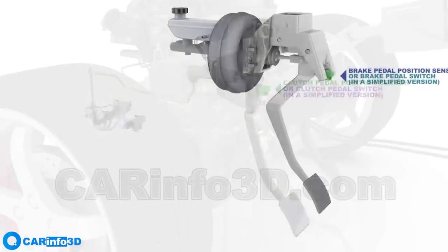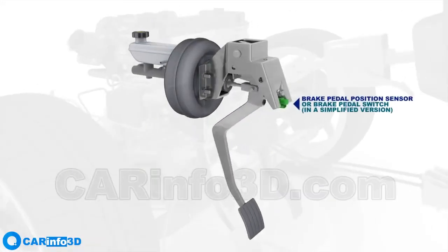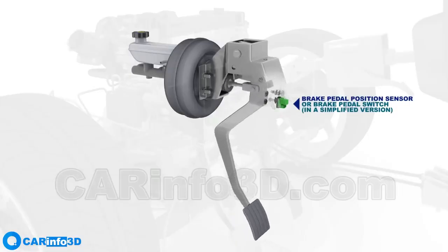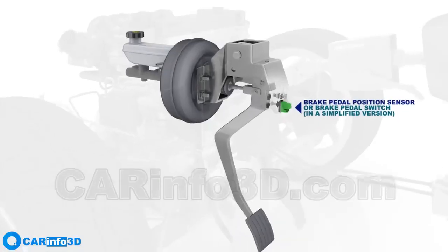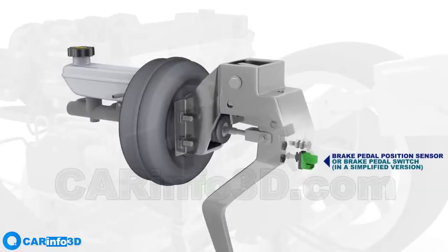Next, the brake pedal position sensor. It is mounted next to the brake pedal. In the most basic configurations, this sensor is a traditional switch that activates stoplights when the brake pedal is engaged. In more advanced systems, the control unit activates the stoplights when it gets a signal from the sensor. It can also perform additional functions, such as sending signals indicating the transient operation of an engine, turning off cruise control, and interacting with the ABS system.